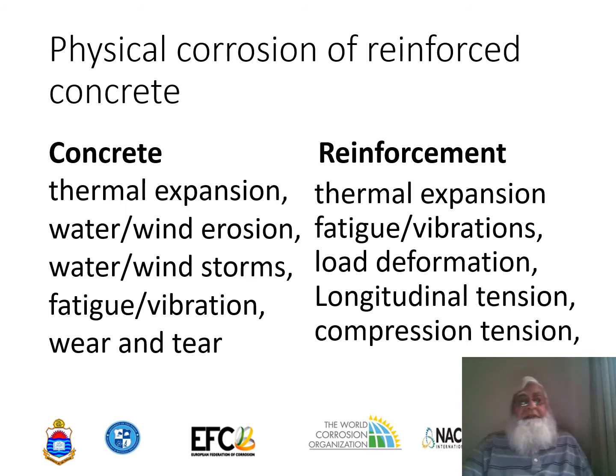Then fatigue vibration comes from natural events like earthquakes and tremors, next-door building works, or heavy machinery in industry, which can cause the buildings to vibrate and the concrete to fail through fatigue and wear and tear, which is very normal in concrete from atmospheric attack.